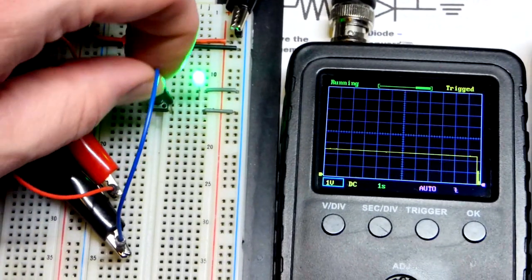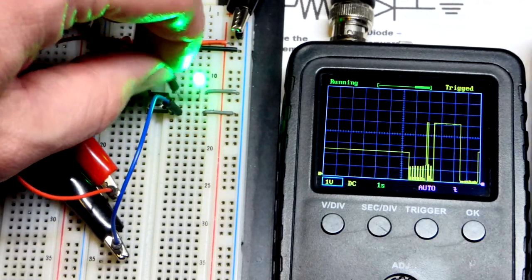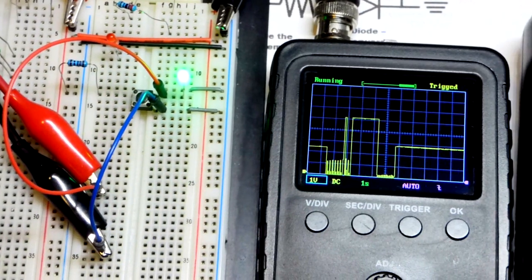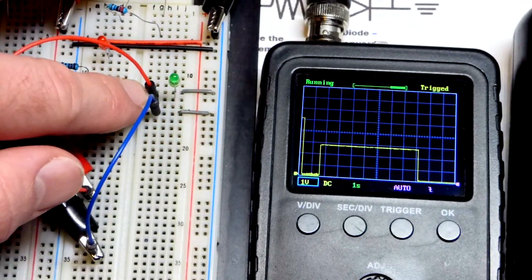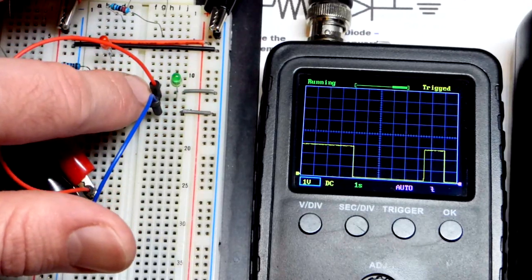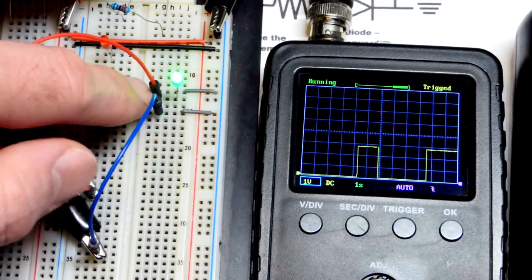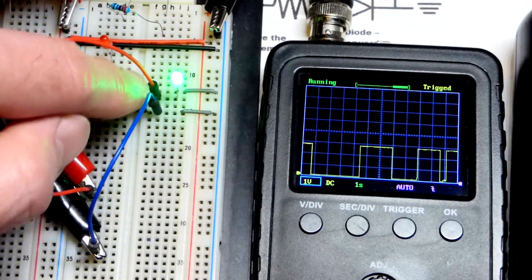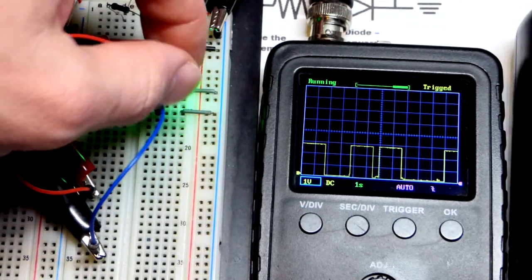But in any case, now we're going to look at what we originally looked at. We've done those voltages in other videos, but it's still a good idea to do them again for review. There we go. We got about 3 volts across the LED. It's lit. That's what it takes to get it to conduct, and then it starts conducting pretty freely after that. The resistor sets the current after that point based on the voltage it gets. I press the button. Now there was no voltage when I pressed the button. So we got a short circuit. When I close the switch, the bottom and the top connect directly together. They connect directly to ground. We have ground on both sides of the green LED.